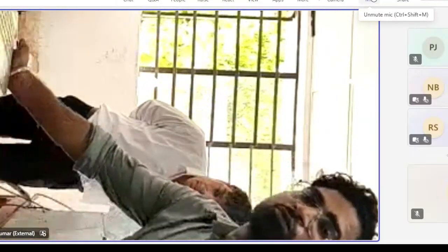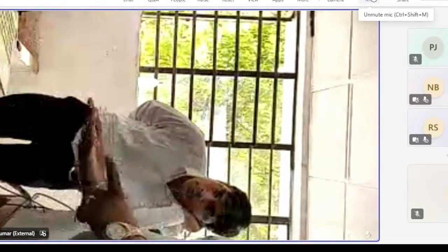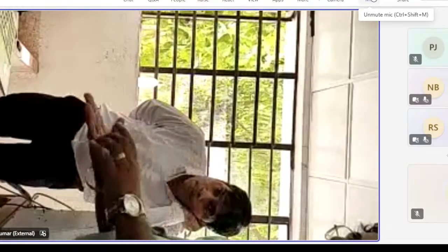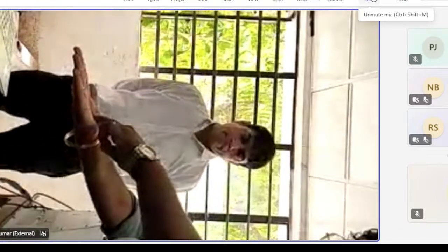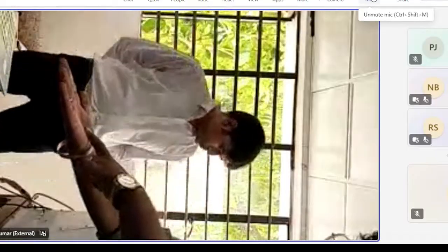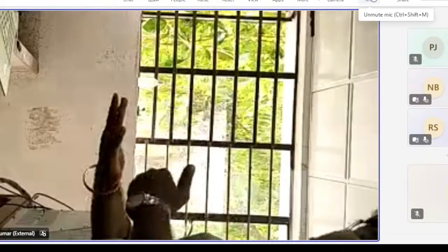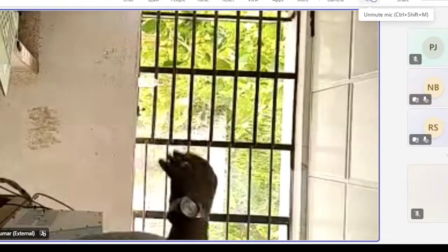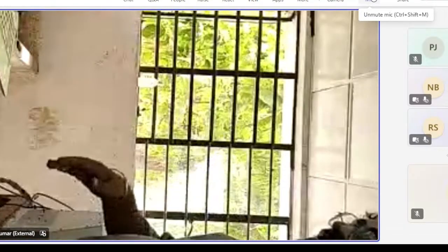Similarly, suppose you want to deposit a single layer bead on a plate over a distance of 80 mm. That means you have to go from here to here, up to 80 mm. So in the programming we have given in the X direction that we want 80 mm, and the speed, that means the travel speed of the torch, is basically 4 mm per second, right?